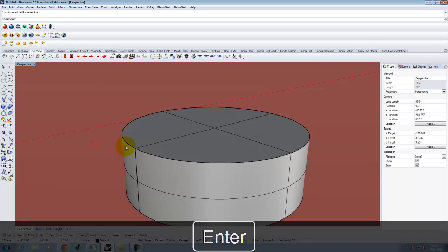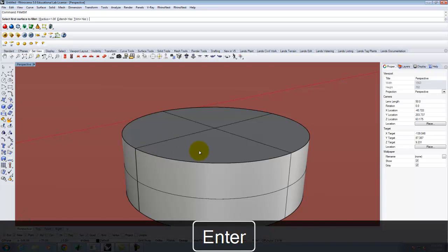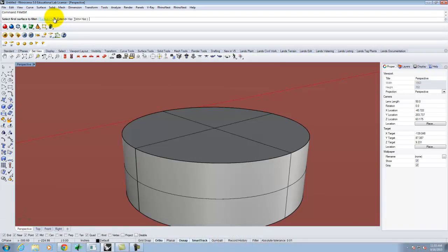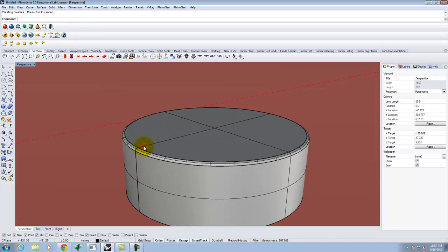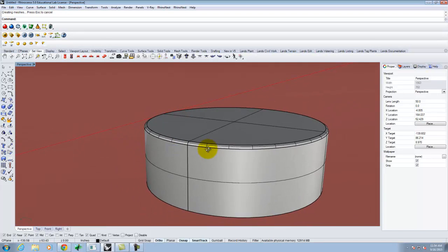And I'm going to use a fillet surface to round over the edge of the table because I want the tablecloth to have a little bit of a round edge to it. Okay? So let me go to fillet surface, and we'll set my radius, 1 inch. It's a little bit generous, but it's going to accentuate the tablecloth a little bit. So we'll go ahead and do 1 inch, and I'll go this surface to that surface, and we get that little bit of a bevel or a little bit of a round over.